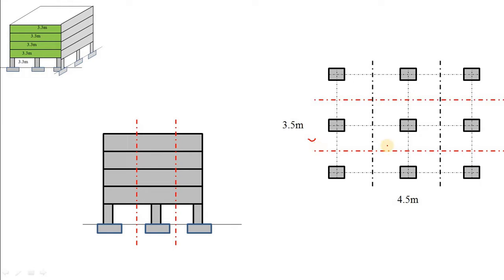Okay, now can you see something special in this plan drawing? Well, let me tell you, the middle column, you can see this. The middle column carries the maximum load and you have already learned how I have got this. So if you design the foundation for this middle column, obviously this will be safe for each of the side column and also the corner column. Why? Because the tributary area for this column, I repeat, the tributary area for this column is maximum, and that's why the method I am using to calculate the foundation size is known as tributary area method.